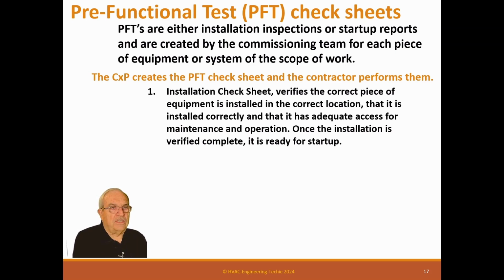Installation check sheets verify the correct piece of equipment is installed in the correct location, that it is installed correctly, and that it has adequate access for maintenance and operation. Once the installation is verified as complete, it is ready for startup. So, you need to make sure everything's correct. And the contractors normally have a pre-startup checklist. Well, this can become that list, but it doesn't have to be. But these need to be done before they start the system up.